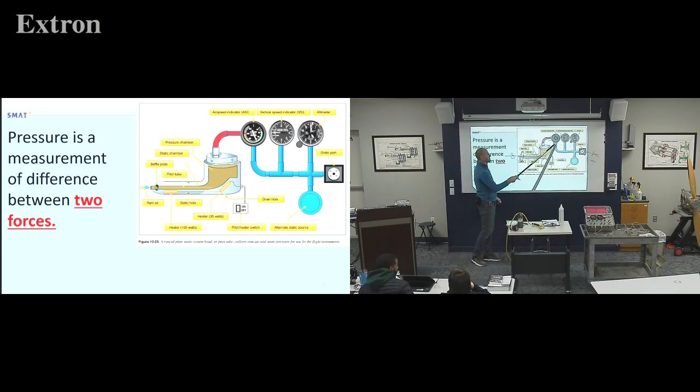So that the pressures are the same, and then you'll run a vacuum, and you just gotta make sure you're capped off here. So then you can bring the altimeter up as high as you want. It's just like putting your airplane on your hand and lifting it up into space, right? We're not hurting anything that way. And then you can plug off your vacuum hose, and if the altimeter doesn't move, you go, oh, no leak.